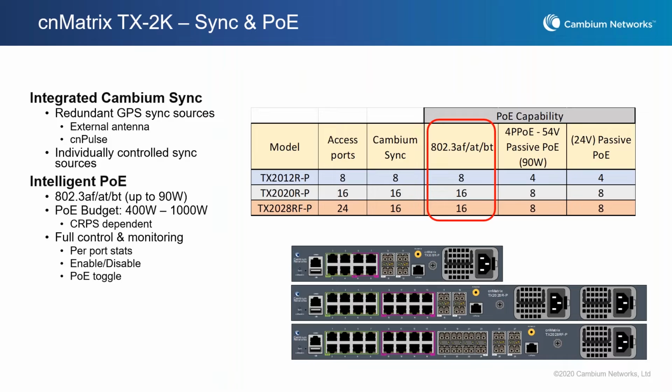From a PoE point of view, let me emphasize again, we support standards-based PoE in addition to the other PoE modes. And more devices are using standards-based PoE. And there's a lot of safety associated with it, right? Within the standard, you have to go through a detection mode and finally connecting and finally delivering the power. So when possible, we use 802.3. And we do support 802.3, so we have a PoE controller on every single port.